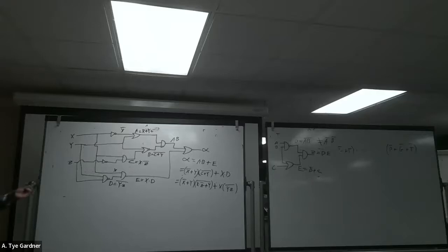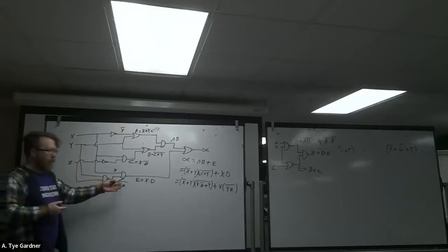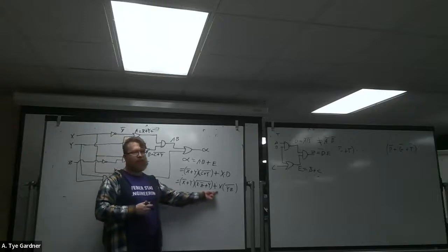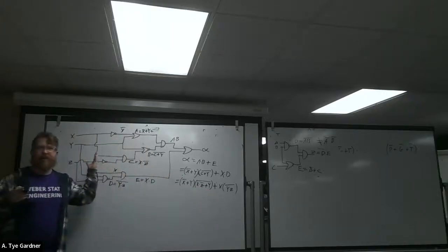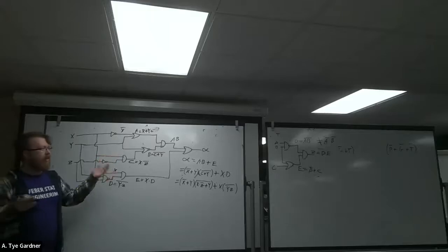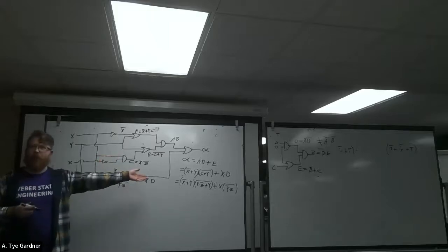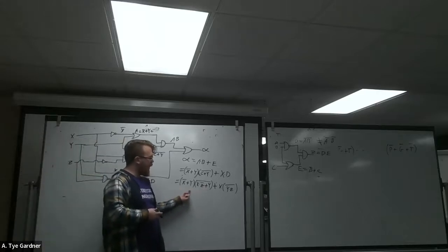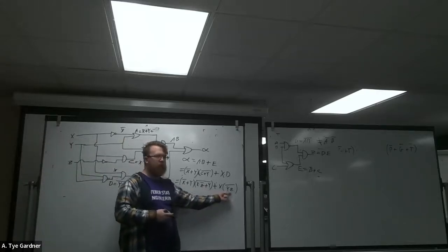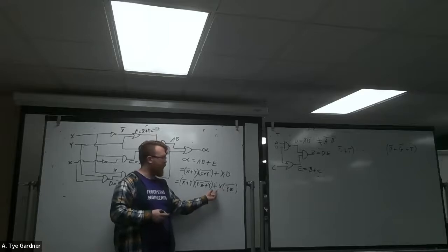Now, we can say that this is a mess of a circuit. And if I gave you this circuit, this equation, theoretically, you could build this circuit off of it. The design part is harder, and the hardest part is recognizing the OR part, which is why I'm going to have you do a lot of design and analysis practice, because you can recognize that this ANDing is ORed, so I have an output OR gate. It's hard to do an AND gate as your final gate.